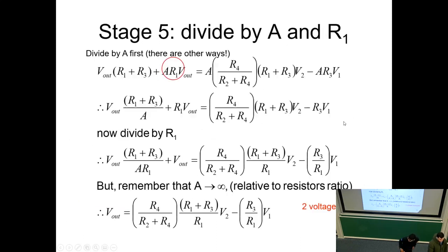Yeah, but what I meant to ask is that we can apply the same basic laws you told us from the very start of the introduction, with the understanding of how an op-amp works. I want to confirm, whenever we say that the input impedance for the op-amp is ideally infinity, that's just a way of assuming that none of the signal is wasted and all of it reaches the op-amp, right? And when we say that Z out, the output impedance, is 0, that's just our way of assuming that there are no loading effects, and it just perfectly gives the signal.